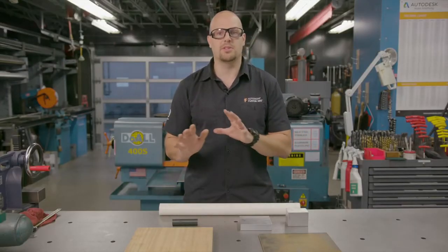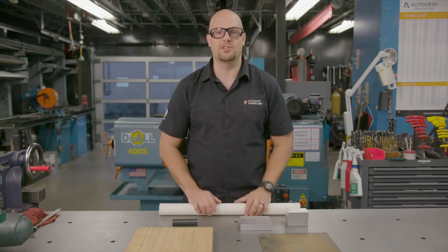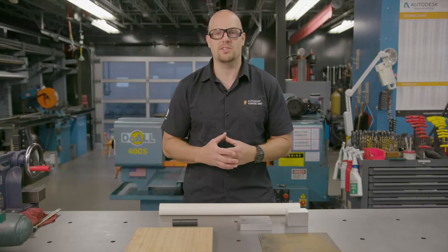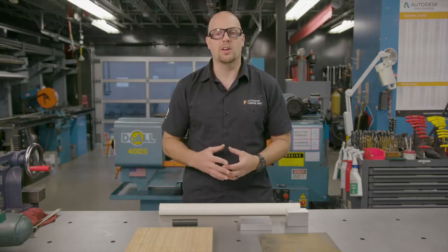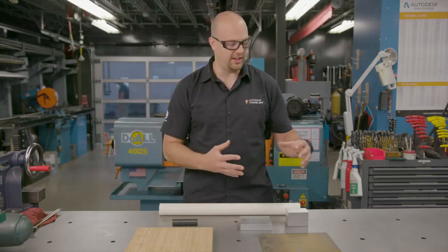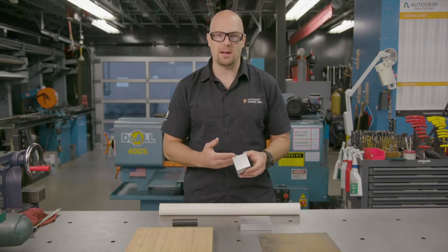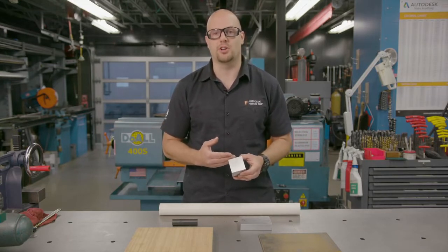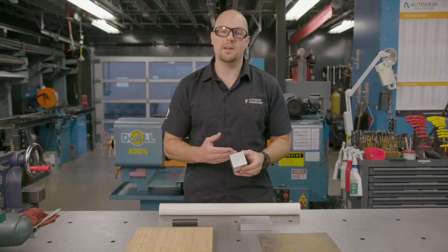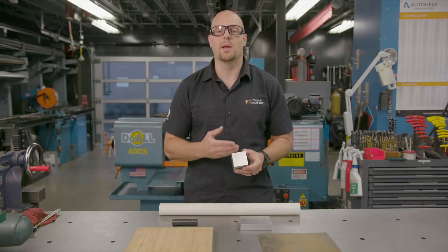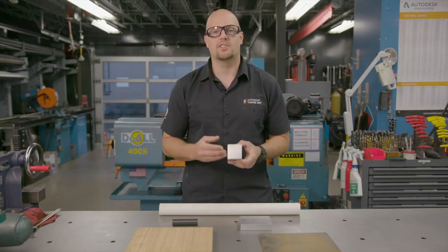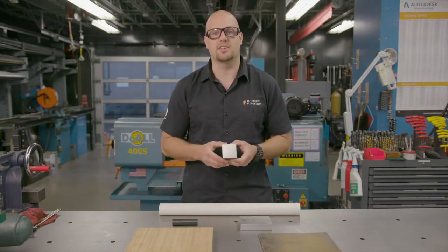Now, stock comes in both certified and uncertified variations that will hold different tolerances, but for the most part, you're going to make the assumption that you have to remove some amount of material to get a perfectly dimensioned surface on your finished part. So keep that in mind when you're designing a part, because stock comes in various standard sizes. Stock can also be had in custom sizes.